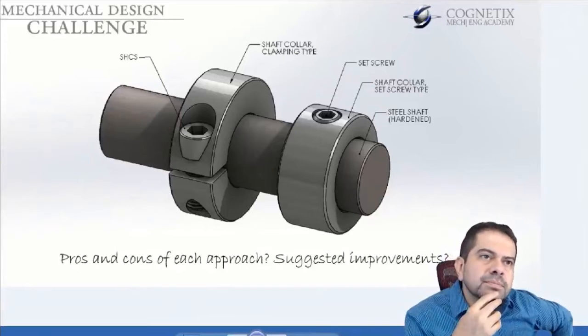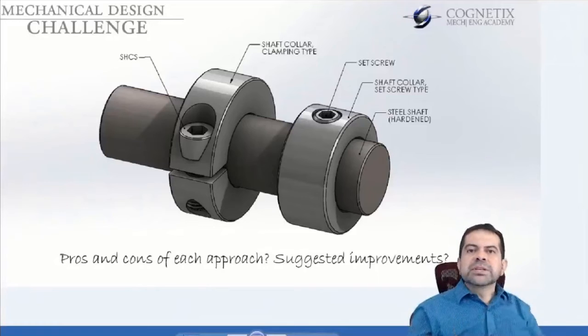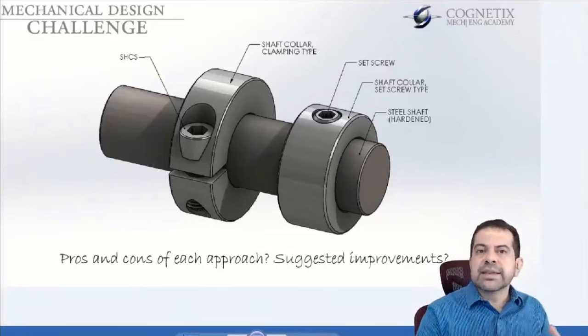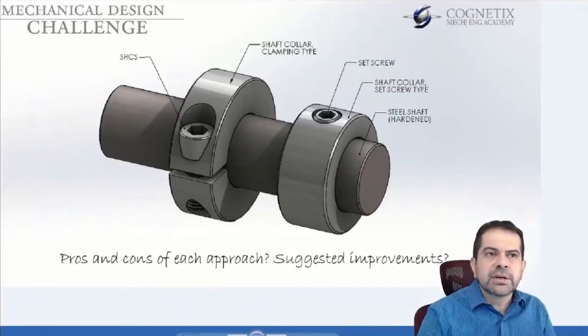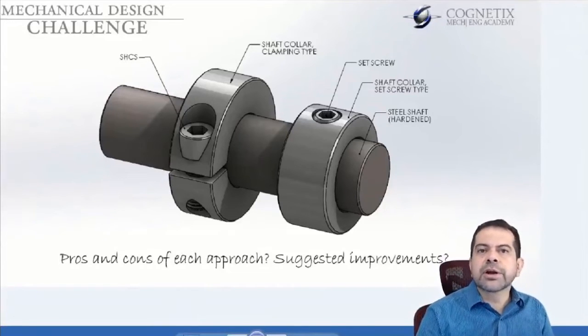The shaft there on the right, I don't know if you can read it. It says steel shaft, and it is hardened. So you can have raw material, raw steel, aluminum, whatever metal you're working with, that is as is, if you will, without any post thermal treatment of any kind. Thermal treatments and other treatments as well are used for hardening. So you can harden either the entire shaft, or you can harden the outside of the shaft only. That sometimes is referred to as case hardening.